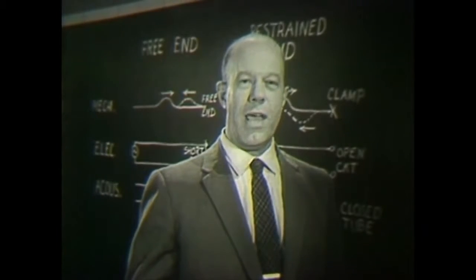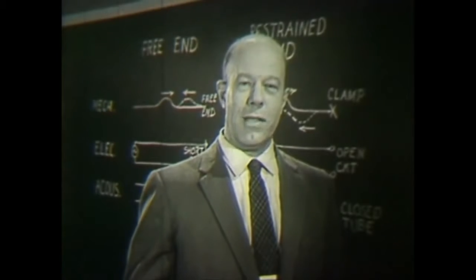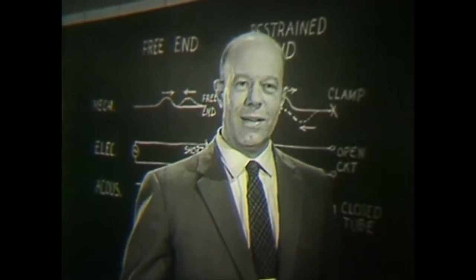Now recall that when we had 100% reflection, when the end of the machine was clamped, we obtained a standing wave pattern with motionless nodes. The standing wave ratio in that case was infinity. On the other hand, when I had a perfect impedance match, there was no reflection at all and no standing wave pattern. In that case, A max and A min were the same, and the standing wave ratio was unity.